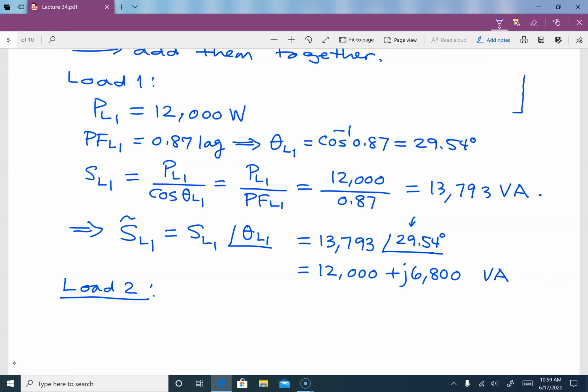Let's say this is the power triangle, the P is known, the angle is known, we need this, right? This is not known. Then you can go with tangent theta equal to Q over P, which means you will be able to find the Q. And when you find the Q and you have the P, then you can end up with this value anyway.